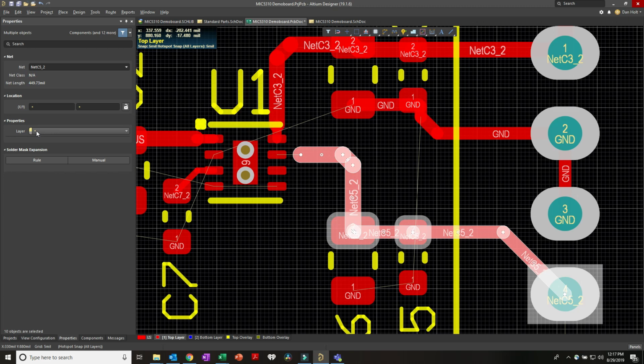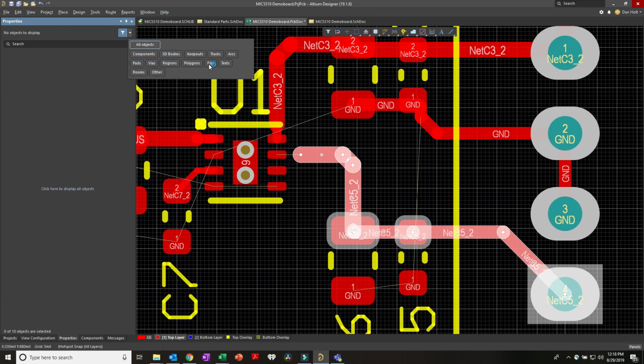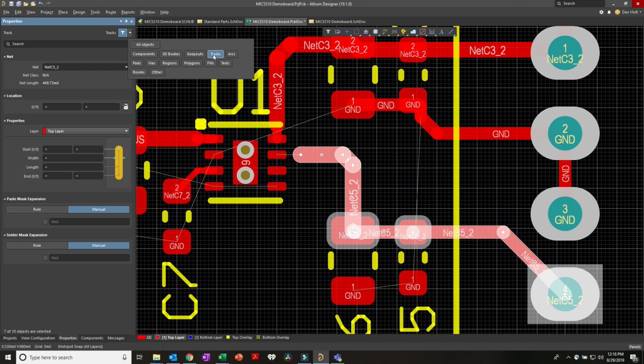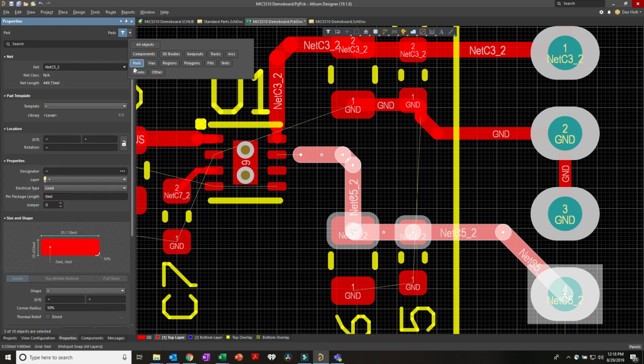Other ways to select a net, you can do S for select, and you can say select an entire net, or connected copper, or physical connection. Connected copper means anything that's copper at all that's touching this node is going to get selected. So all of this has been touched. This includes pads and vias, so I can't change the size of the via or the size of a trace because I have too many different things uniquely identified. So layer is really the only thing that's even kind of common.